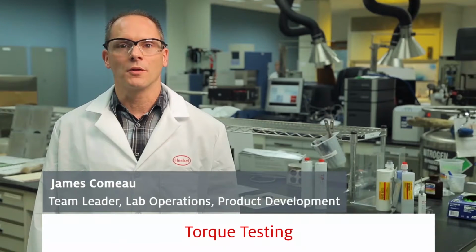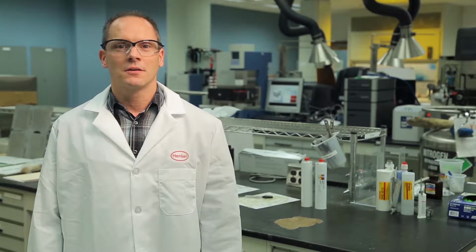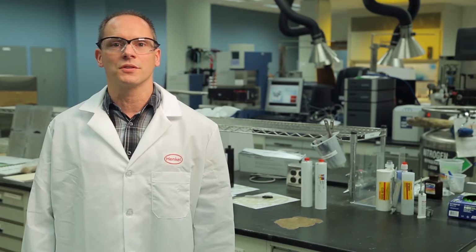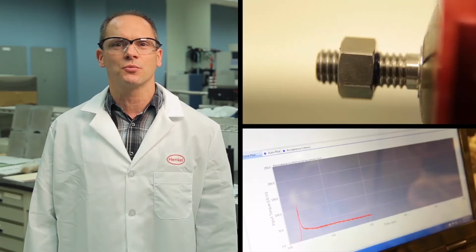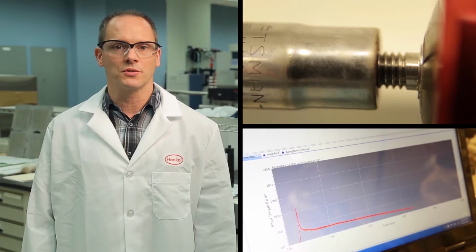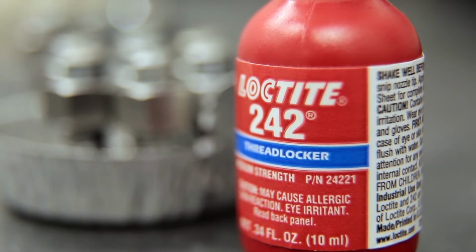Threaded fasteners are one of the most important detachable parts used in machinery construction. The functional reliability of threaded assemblies rests on the torque forces applied along its axis, and can be compromised when either tension is relaxed or the part self-loosens. A thread-locking adhesive helps restrict lateral movement by filling the gaps and limiting slip in the thread.